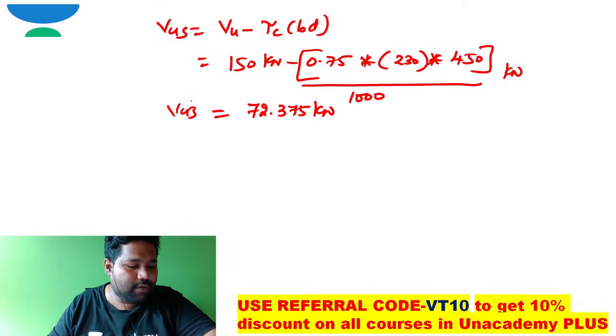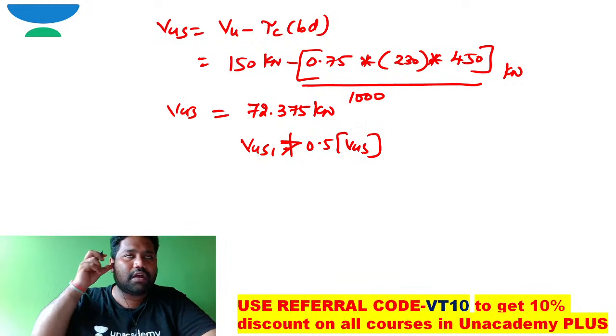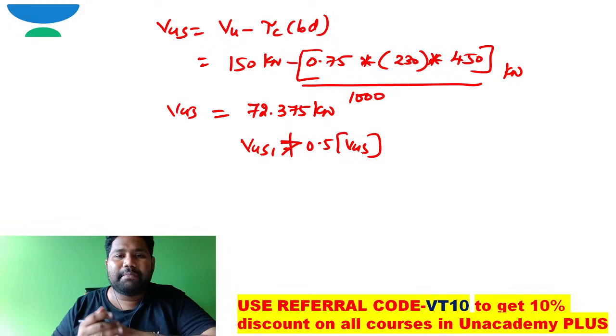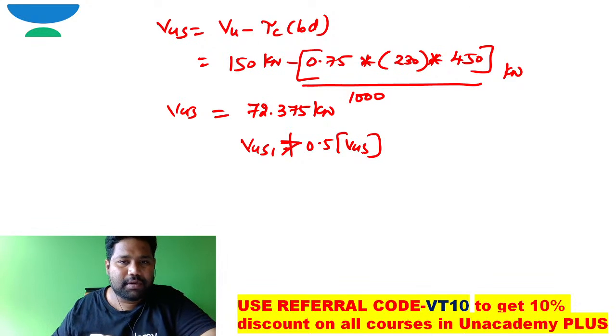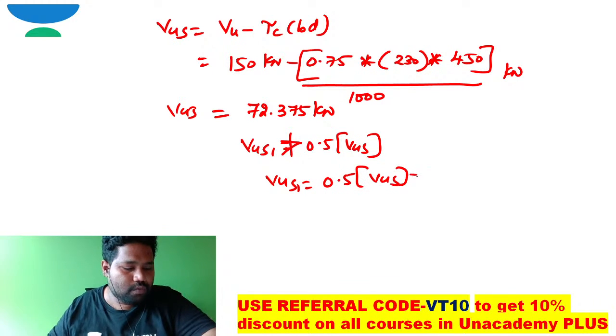But there is one condition: VUS1 should not be greater than 0.5 times VUS. The shear strength of the bent up bars at maximum is limited to 50 percentage of the shear force to be resisted by shear reinforcement. So VUS1 is equal to 0.5 times this, which is 36.18.